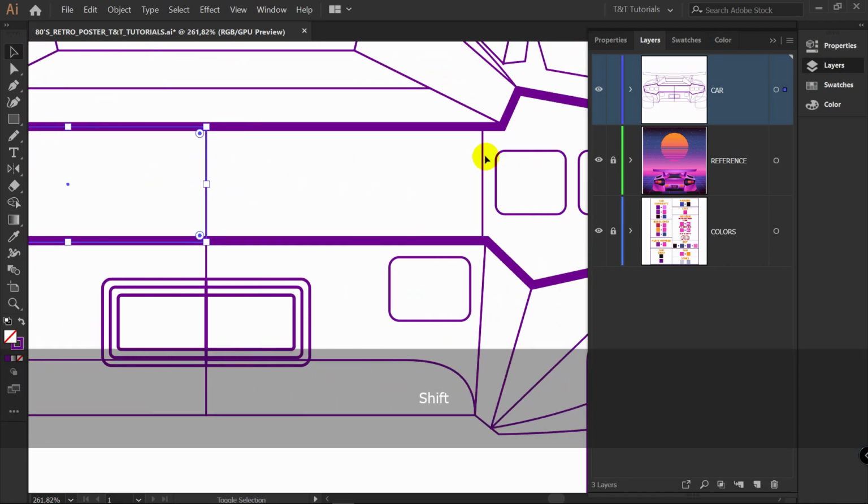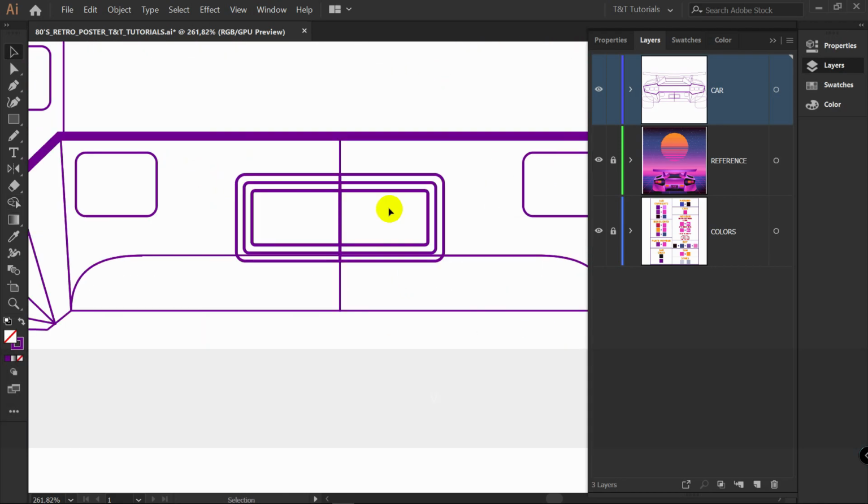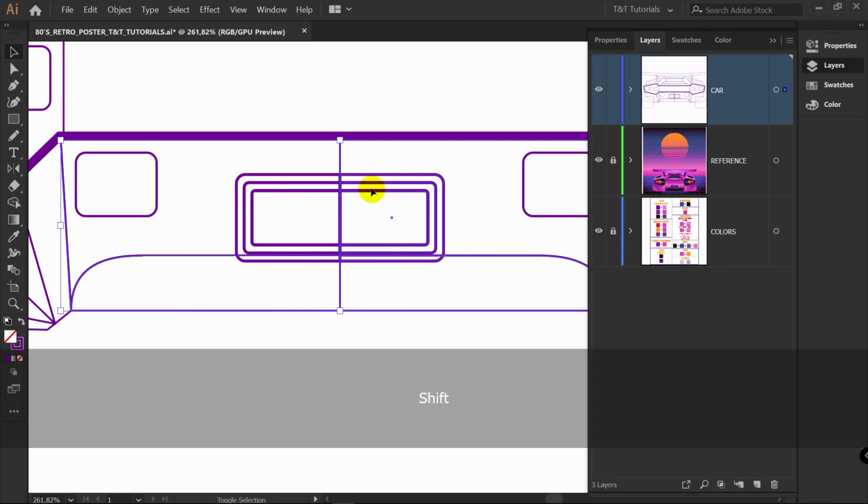Now select these ones. If you can't pick layers that you need, for example we need these 2 layers, just select all layers, hold Shift and remove unnecessary layers from selection. Now we have only these 2 layers selected, Shift plus M, and unite them.